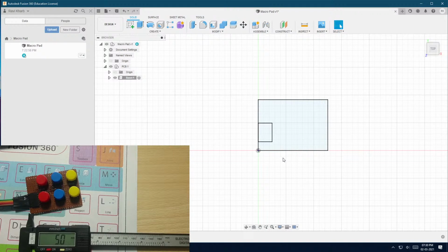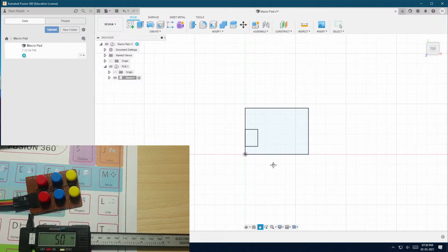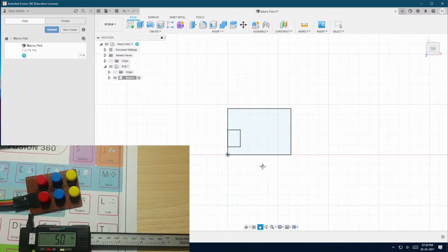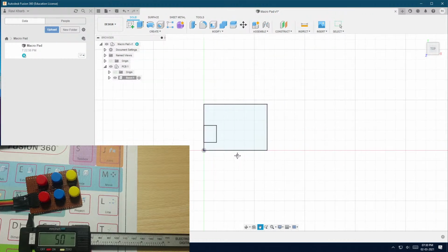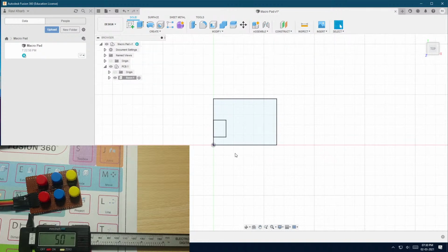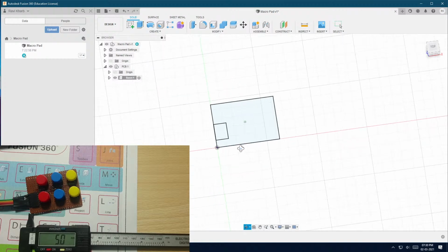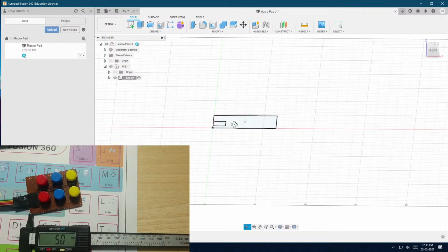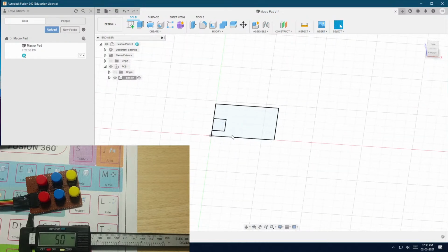And how do I rotate, actually? That's just selection. Okay, I can move with the middle mouse button. Let's try shift. Still selection. Yeah, shift plus middle mouse button lets me rotate the camera view.